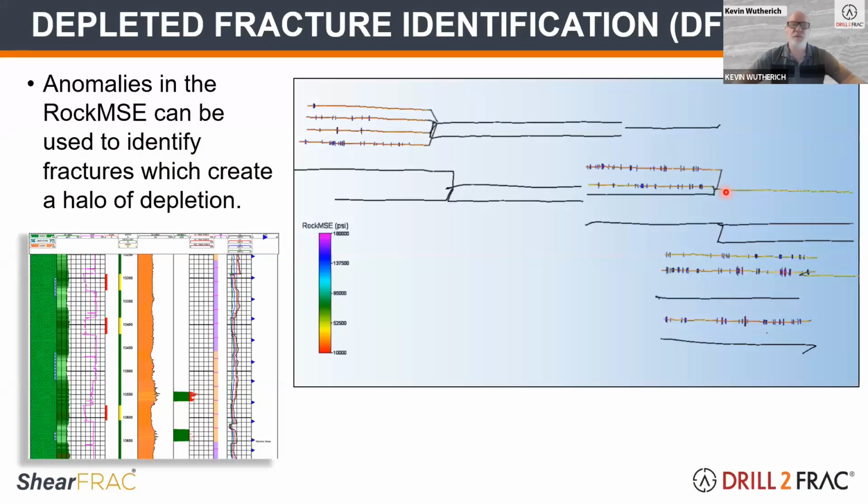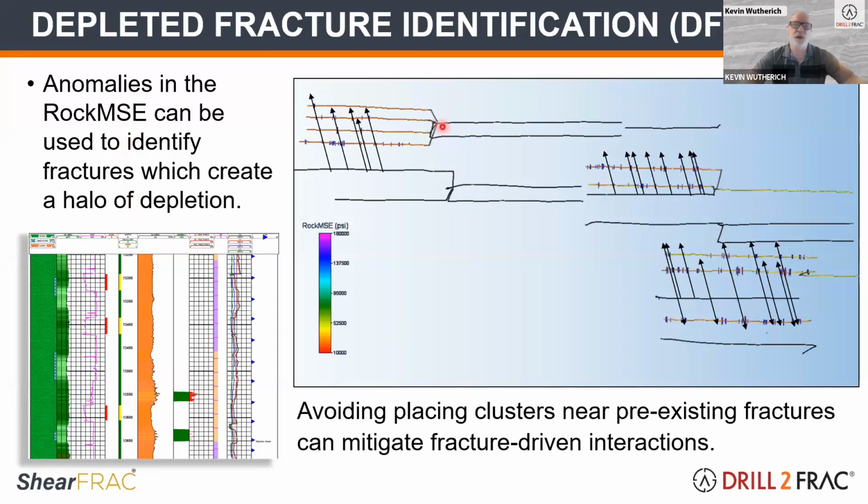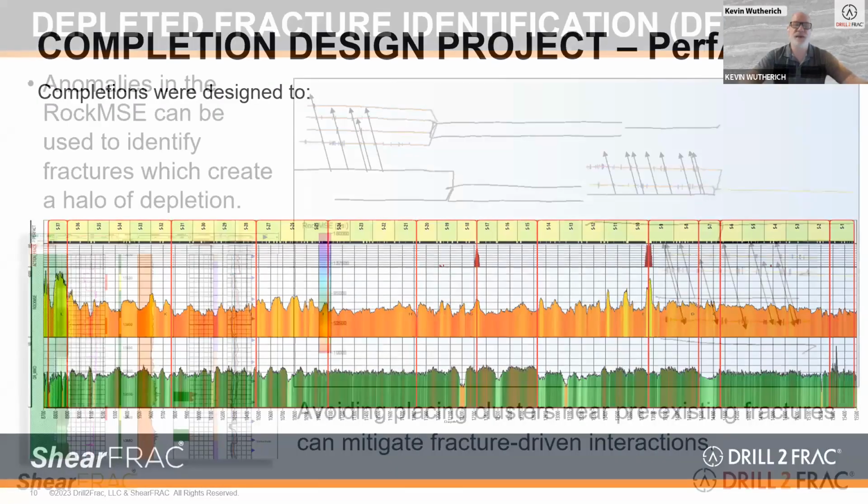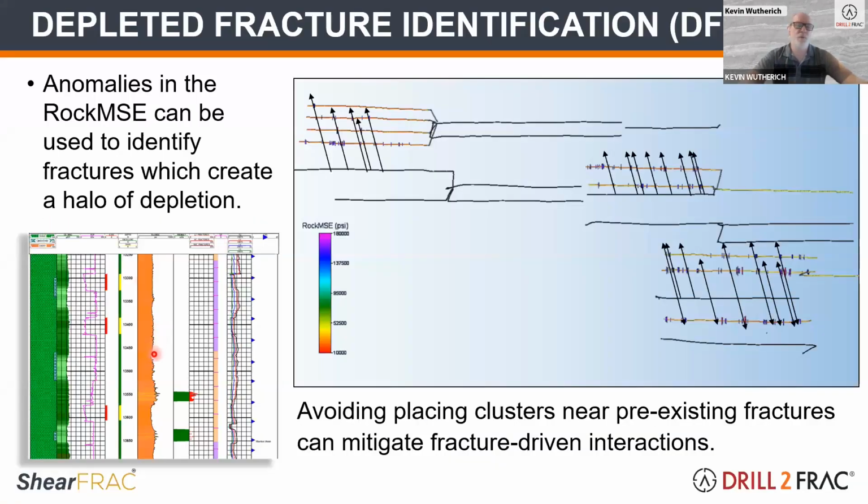The next thing that we look at, and something we've been doing a lot with our company lately, is looking for localized depletion. So when we take that rock MSE that we measure, what we found is that as you drill through localized depletion, it takes more energy to drill through that depletion.